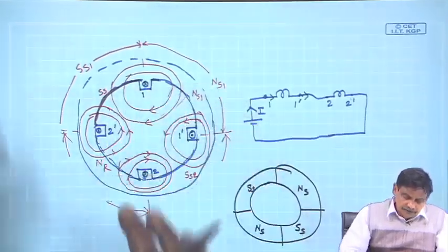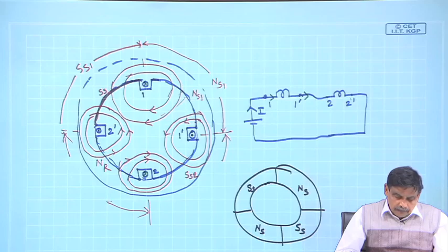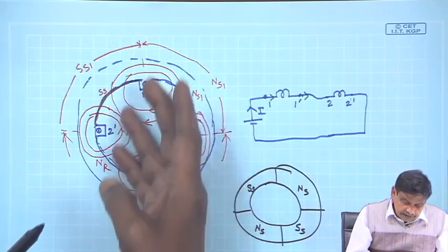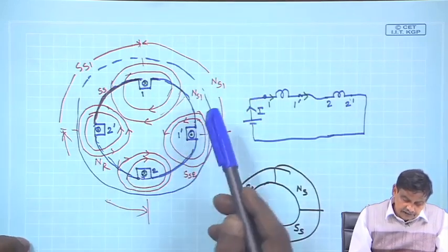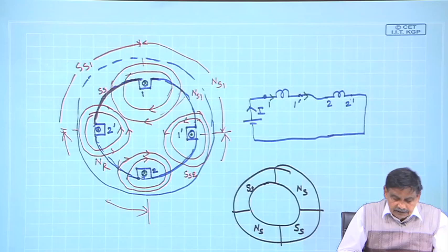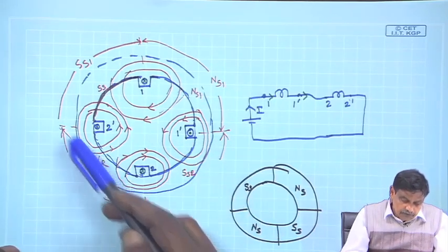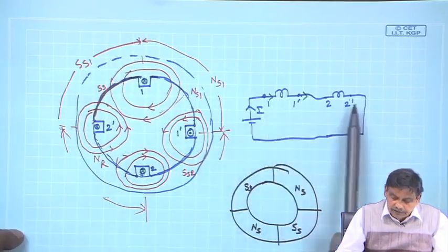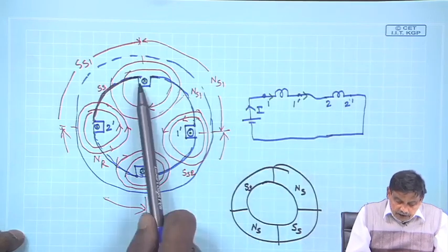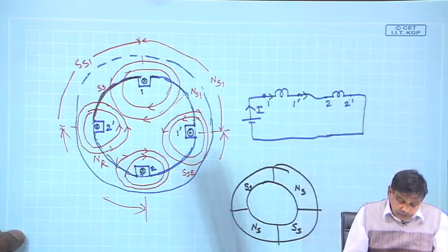In this diagram I showed how you can produce a 4 pole field by, say, a rotor here. It is a rotor coil, and it produces a quarter of this space as north pole, the next quarter as south pole, another quarter north pole, another quarter south pole. But to produce that you now need 2 coils. One coil is 1 dashed, another separate coil is 2 dashed.